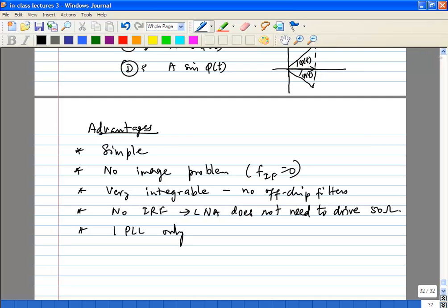It's more sensitive to noise. Why? Higher frequencies. What kind of noise? You mean noise in the PLL or noise in the incoming RF signal? Because at this high frequency, we have more parasitics, so maybe performance is not that good. The typical IF frequency would be maybe 100 megahertz at maximum, but it will typically be much lower. So the LO frequency itself would be approximately the same between the two. They won't be very different. So this RF PLL you will always need. In the other case, you will need a second PLL to demodulate again at the baseband.